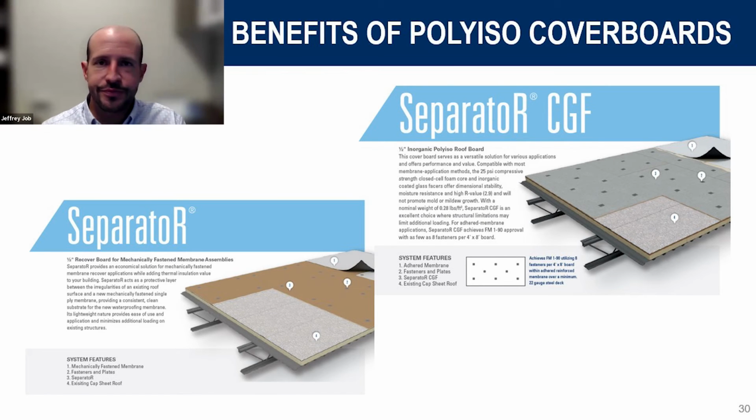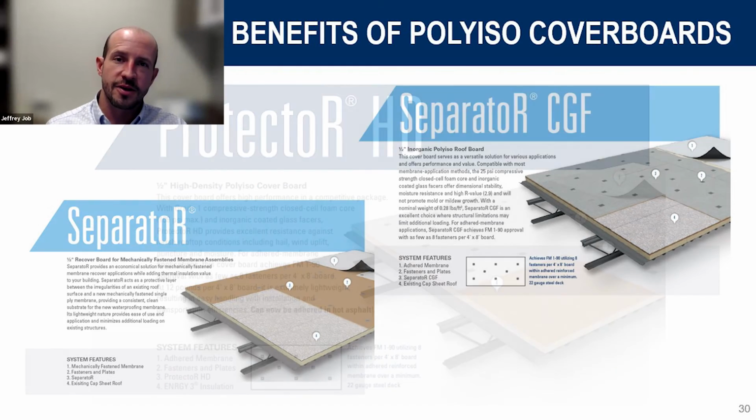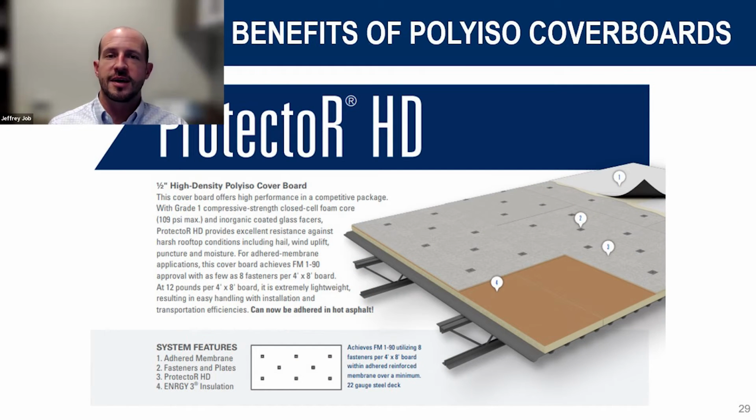So lightweight's a nice benefit there, as well as the ability, from a logistics standpoint, to control how much material you can ship or load a roof with. We've had a number of applications this year where they couldn't point load the roof at a certain weight. So they had to either reduce the pallet size of a gypsum board, or spread that out, or we couldn't simply load the roof deck with traditional pallets. Generally with polyiso, that's not an issue.